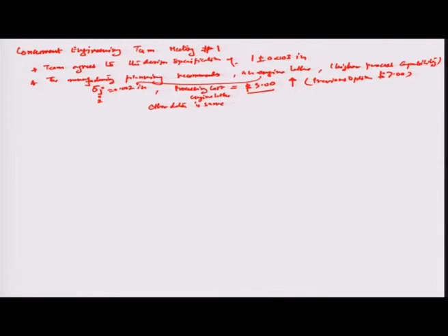So, let us say if we use j equal to 2 for the specification k equal to 1, the ZU21 happens to be 1.003 minus the process mean 1.00 divided by 0.002. So, this happens to be close to 1.5.